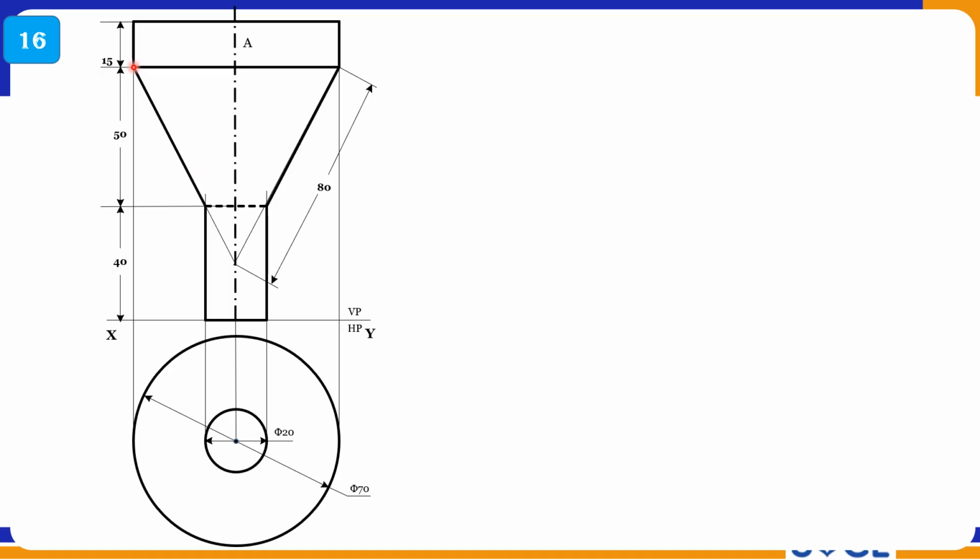So to get the slant length of this cone, you project this up to the axis line. This side also you project up to the axis line. Now measure this. I am getting 80 mm. So slant length is 80 mm. So you can easily measure the theta now, right? Theta is r by L into 360, where r is the radius, 35 mm here, and L is 80 mm. That gives me the subtended angle for this cone.